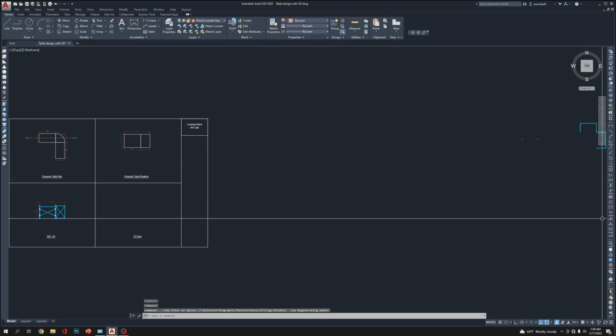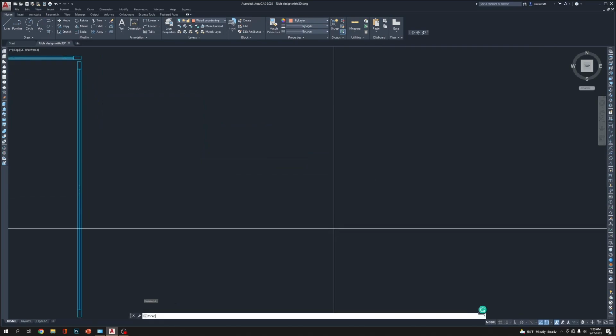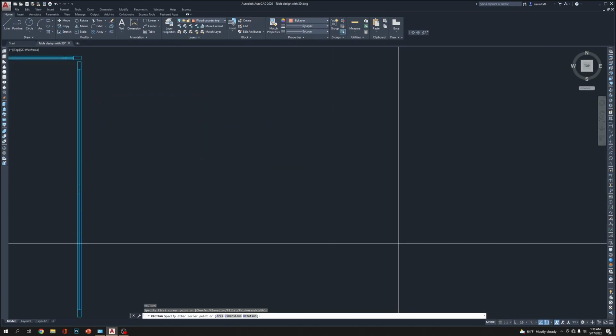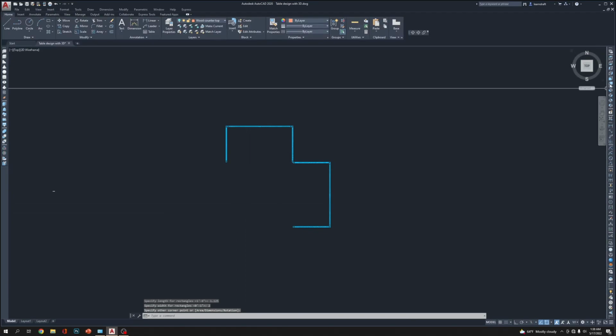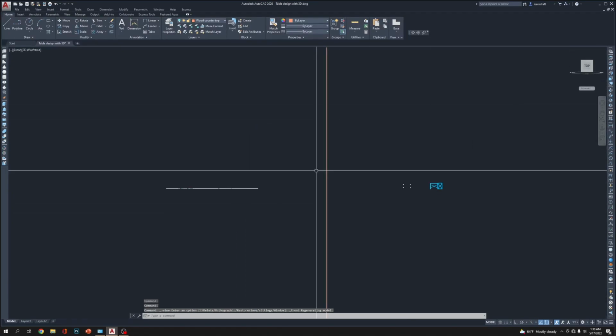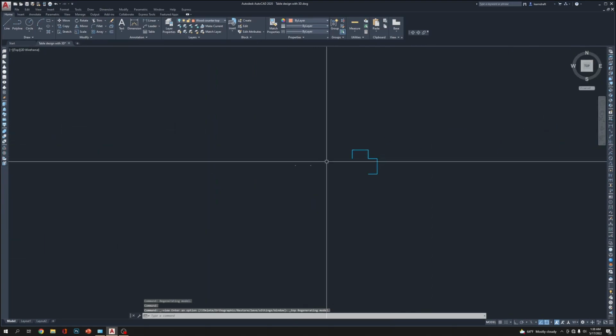Click on the top view, go to wireframe, bring it here, a rectangle, D, enter, 1.125, enter, 2. Guys, my rectangle is going somewhere.